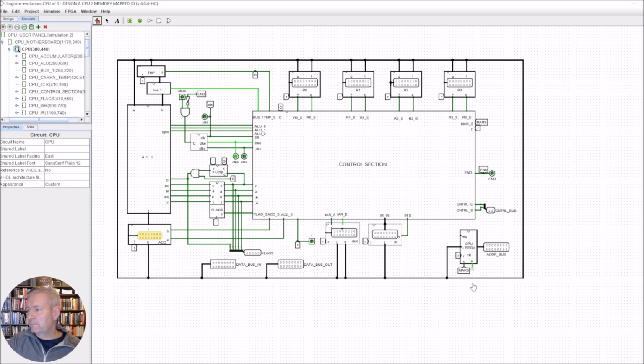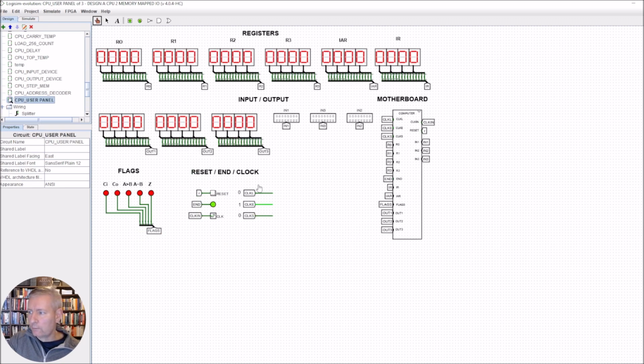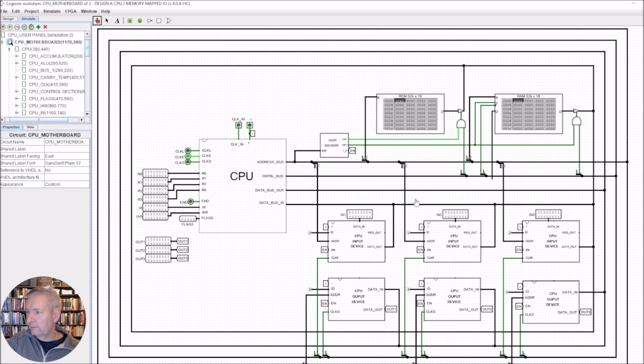Now the address bus in effect starts here, because we take a copy whenever we're looking at an address and we put it into this memory address register, and it heads out in a separate pin, and this becomes our address bus. So that's the only differences really here that you see from the previous video. So let's go and we'll head up to this level here.